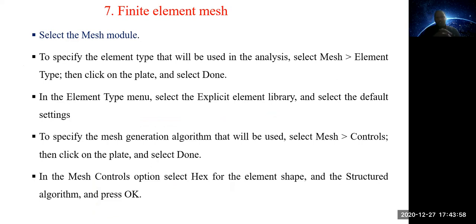So mesh means, as we know from the finite element course, that we discretize a given volume or geometry into any number of elements for simplification of the analysis. We will see the individual element properties in order to evaluate the whole system. So we have to mesh the system. That means we have to discretize it and provide proper material and mesh control.